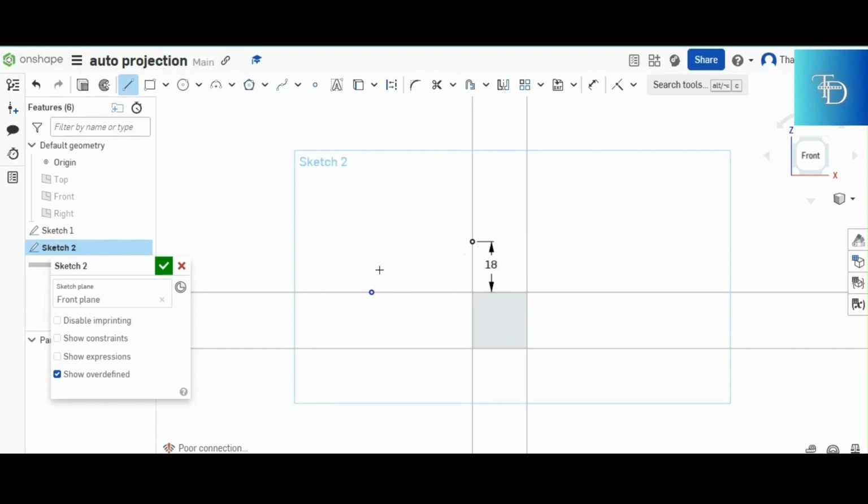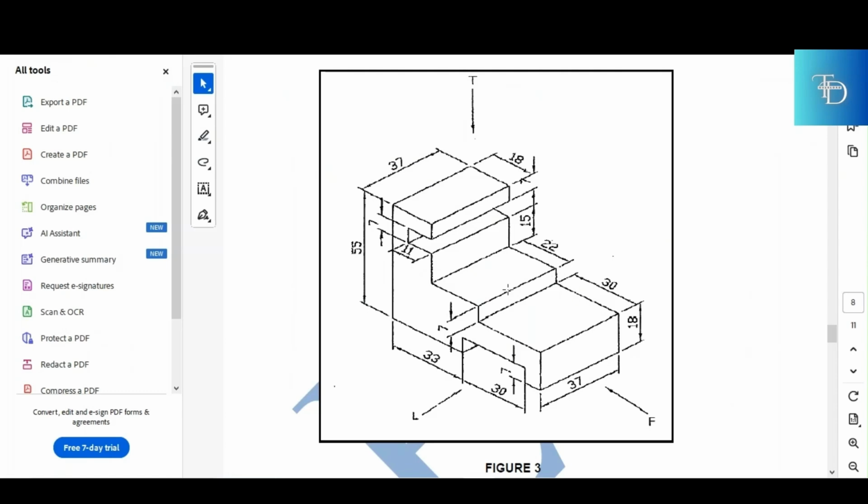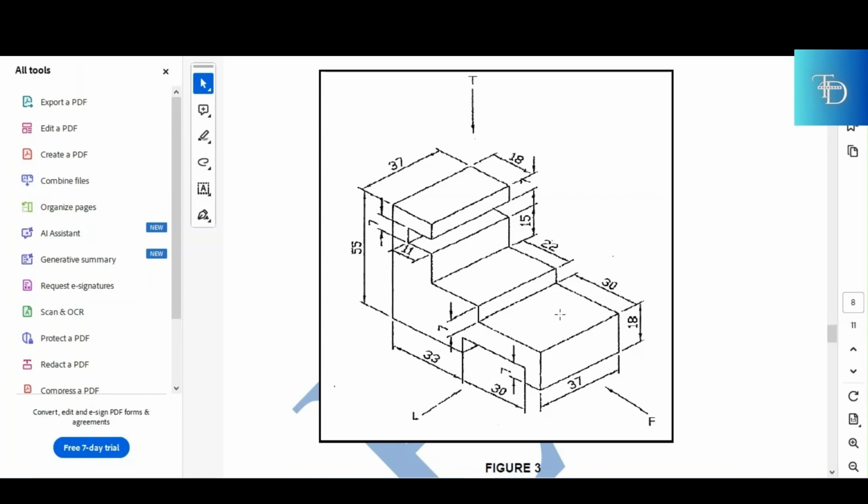And then you create your first surface that you're going to see, which is that rectangular surface right there. So you go back to your structure, you analyze the second one. The second one is pushing up by 7 units. So it goes up by 7 units from the top level of the first one. Which means from the top of the 18, you should also push up by 7 units. Neglect that surface over there, you're not going to see it. When you're standing right there, you're only going to see rectangular shapes stacking on top of each other. It will be like this rectangular shape on top of this one when you're standing at your front view. You're not going to see that thing. You don't include it because it's only visible when you are looking at it from the top side.